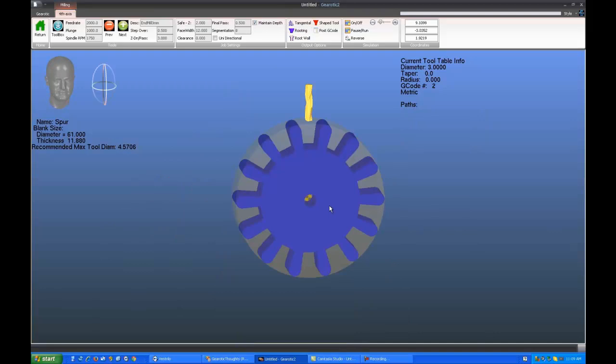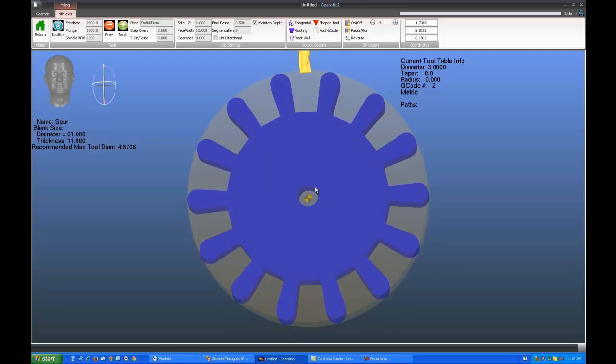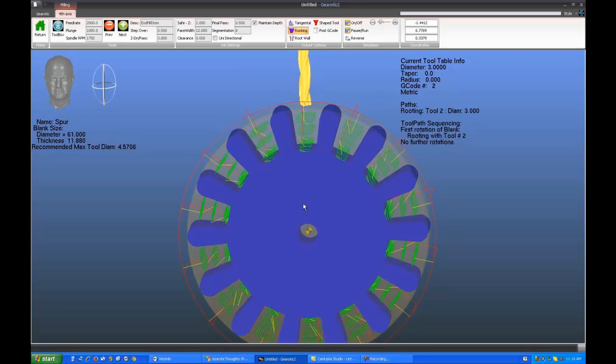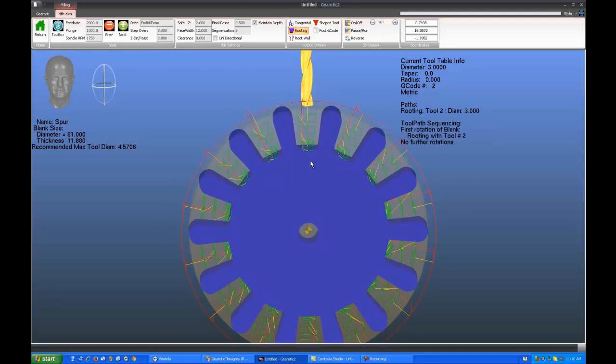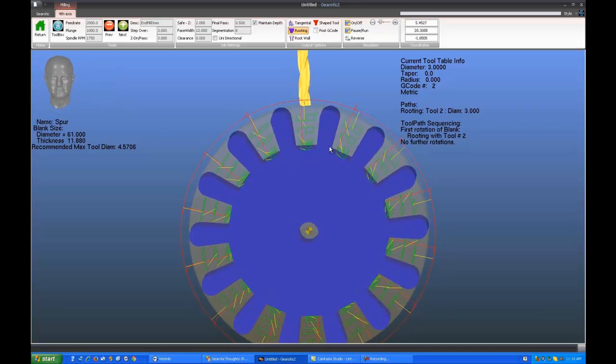So let's do one gear which is not an involute, so that we get the idea of what happens with that gear. Here is an epicycloidal clock gear. And as you can see, I'm just going to select a routing path here. And as you can see, the routing works just as well, if not better, than on an involute, because the roots are quite radial on these gears. Let's get a larger step over. And there we have it. That looks pretty good and is going to clear the root. It should be obvious to everyone that you've done a good pocket on it.